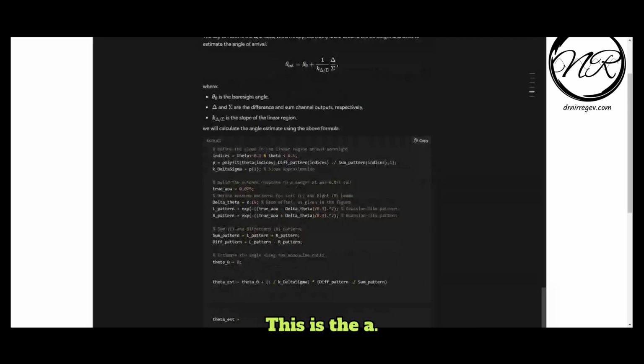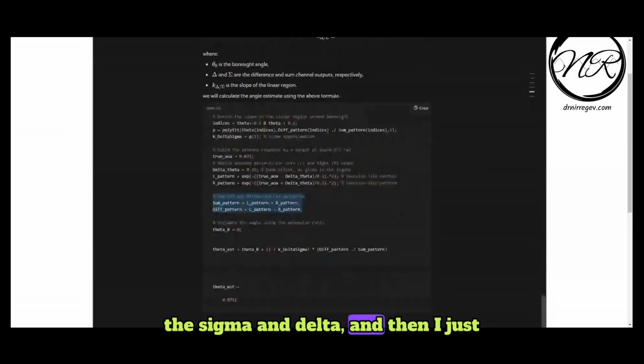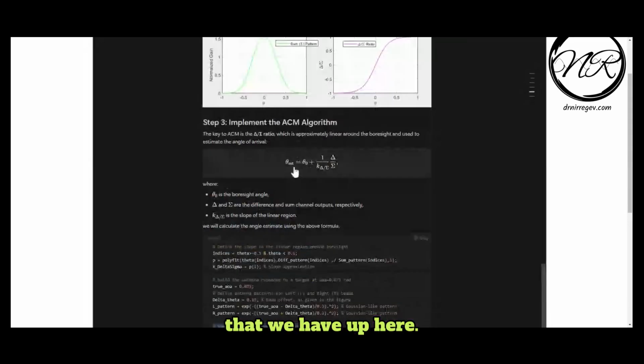Now I test this algorithm. I plug in a true angle of arrival. I get the powers in both left and right antenna or beam, and then I calculate the sigma and delta, and then I just plug it into the formula that we have up here.